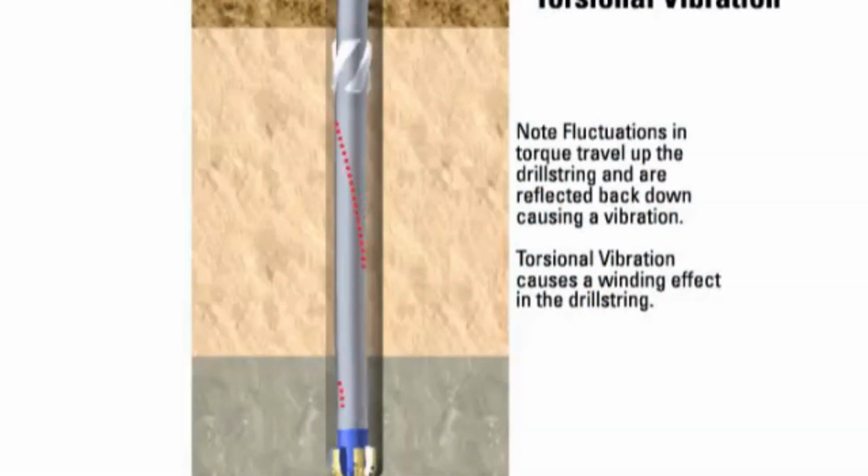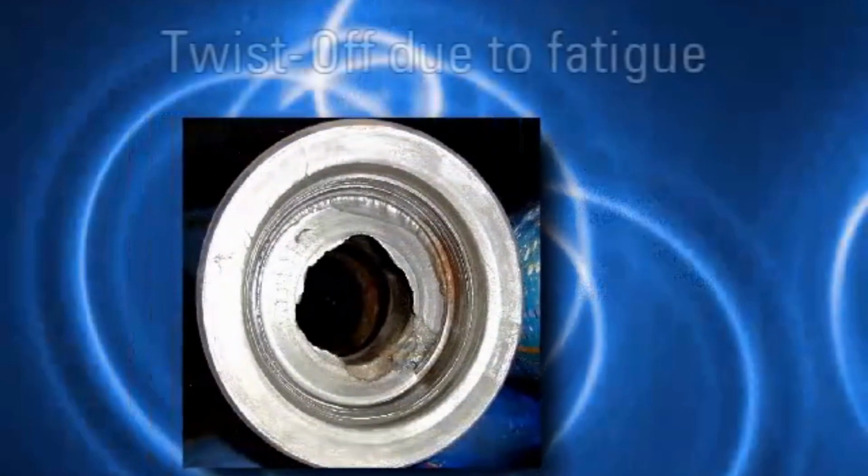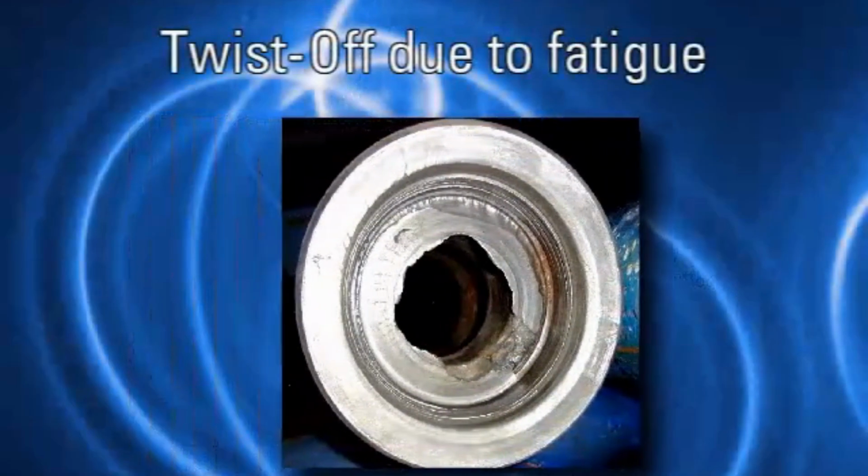Torsional shocks result from the momentary slowing down or stopping of the drill string. This occurs when the bit digs into the formation deeply enough to slow it down relative to the drill string, or when a stabilizer digs into the formation. This causes a winding effect in the drill string, which can fatigue the drill string and BHA.